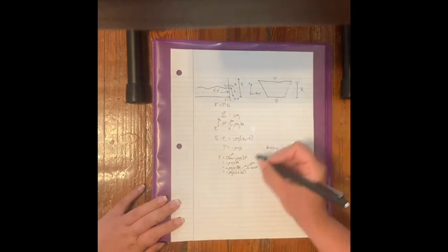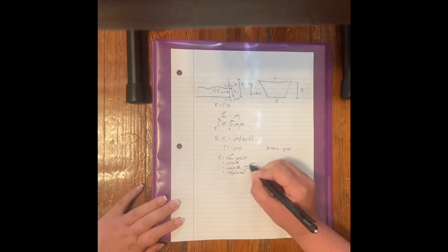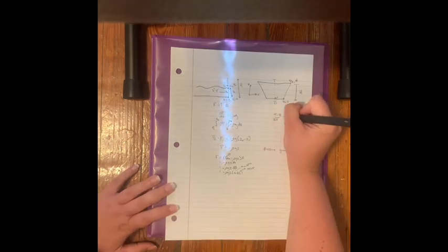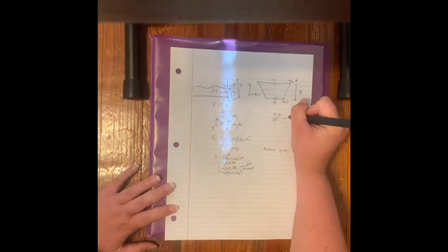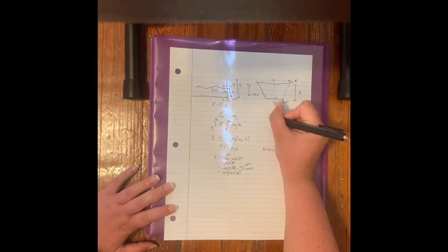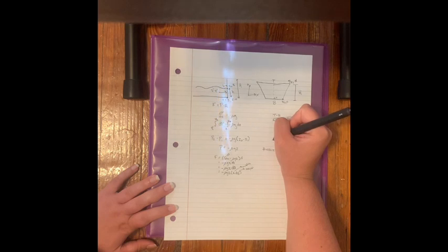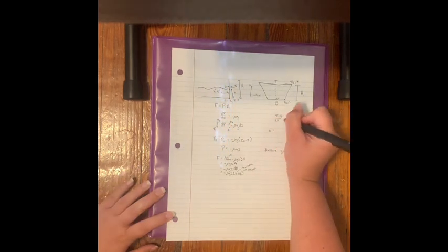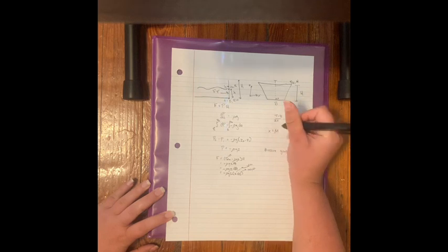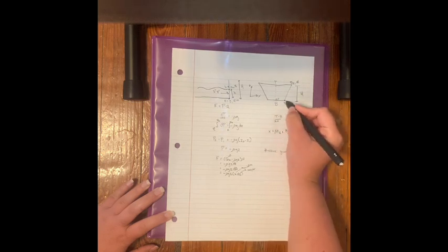Because our shape is a trapezoid, our width is going to change with our height. So we need to find a way to express our width in terms of z, our height, to put into this equation. And that will be our slope. We're going to write this as capital M throughout the remainder of the problem until the very last step, instead of writing this entire portion. So then what we get for the equation of the line is x, which is our width, is equal to capital M, this part here, times the height, plus the bottom width here divided by 2. To find this equation, we used this point here.